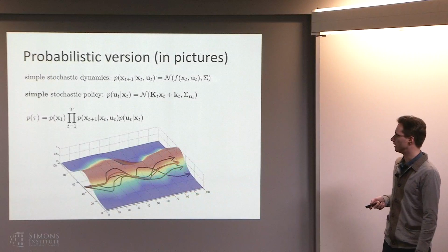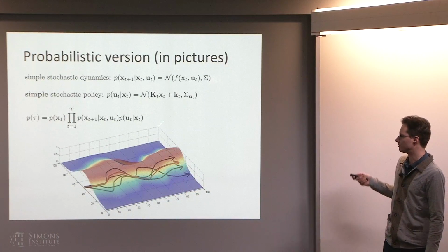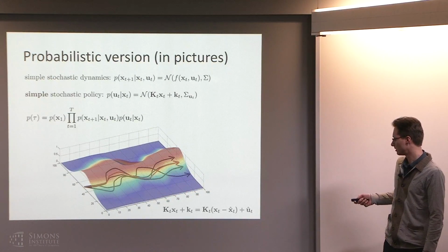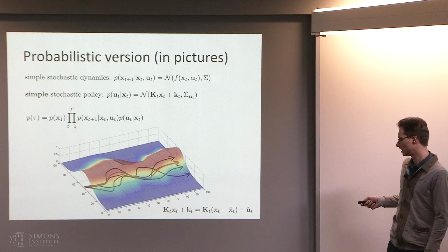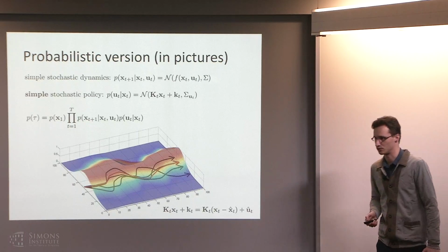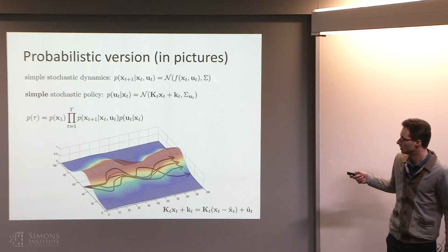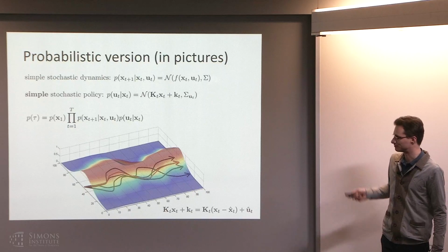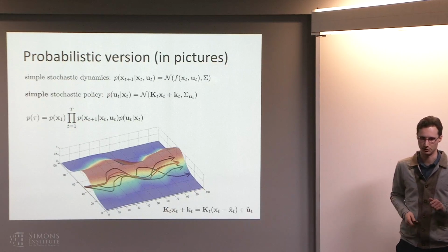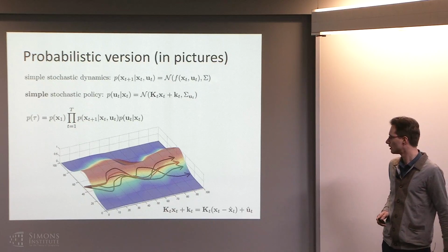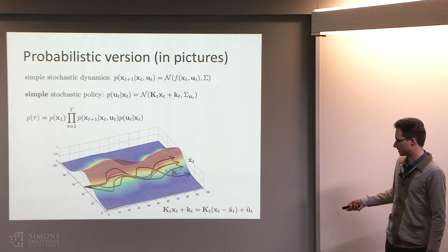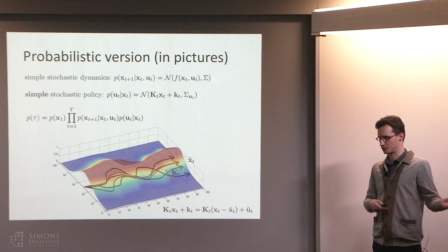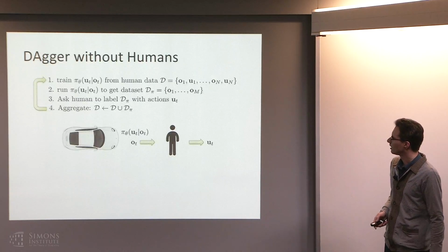There we were training this time-varying policy with optimal control that basically looks at the current state, sees how much it deviates from the desired state, which came in the running example from the mocap data, and then applies some little feedback matrix to it, which you can optimize if you know the dynamics distribution up here. Okay, I'm not going to get into it too much because that's just optimal control stuff. So the linear feedback pushes you towards that mean. And that's where the stability there came from.